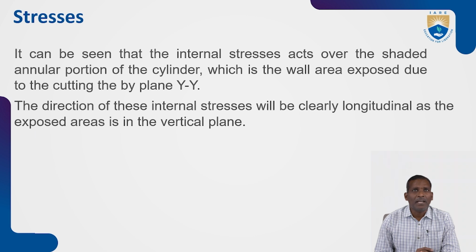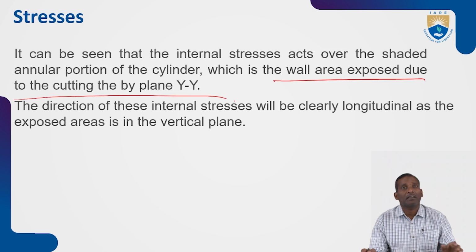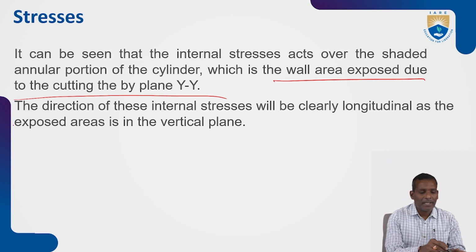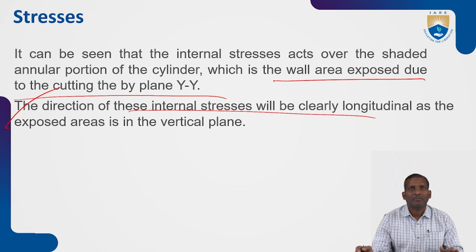It can be seen that the internal stresses act over the shaded annular portion of the cylinder, which is the wall area exposed by the cutting plane Y. The direction of these internal stresses will be clearly longitudinal, as the exposed area is in the vertical plane.